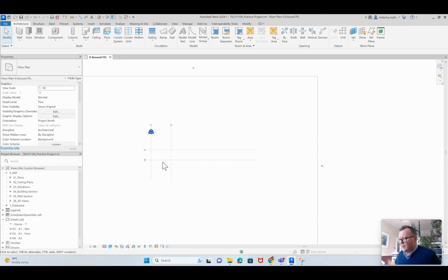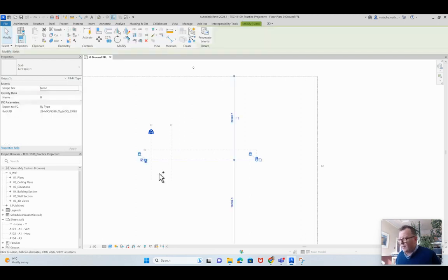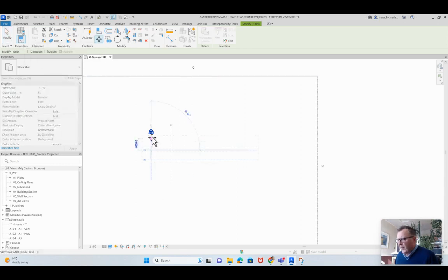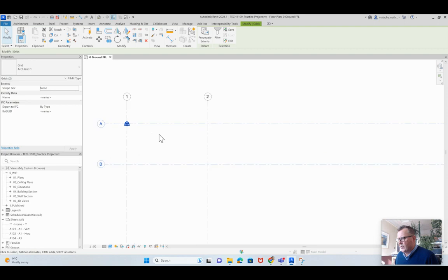Right. Now, just for me, I'm going to pick this one and this one. Okay, so see the way I selected 2. Selected 1, if you hold down the shift key, you can see the little plus button. That means you can add to the selection like so. And when you do move or copy, you always select the items first. So here's my move tool, and I'm going to move that up into that position there.